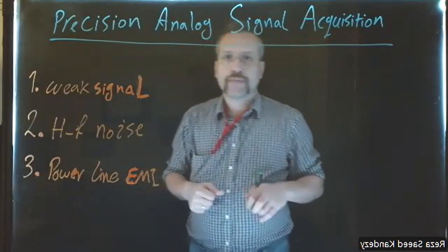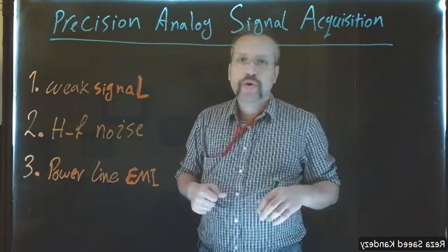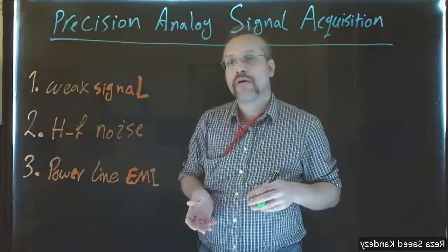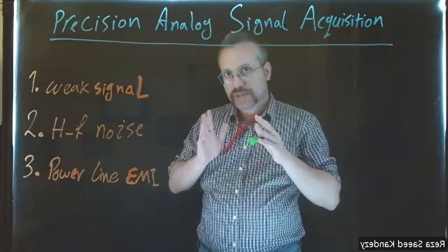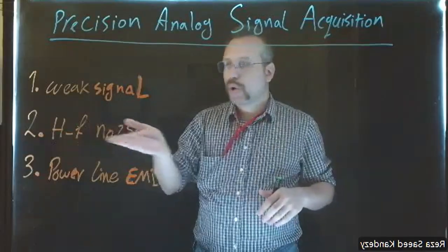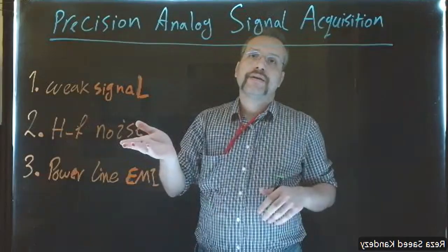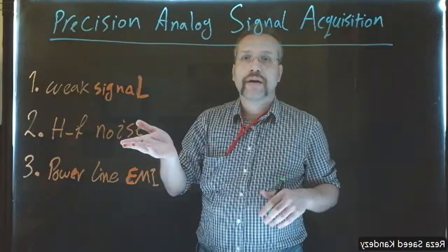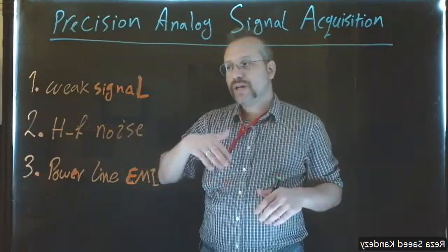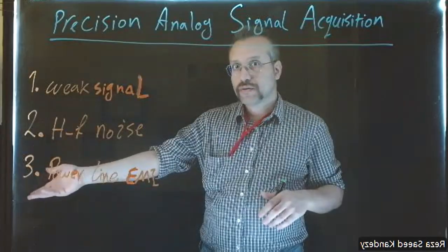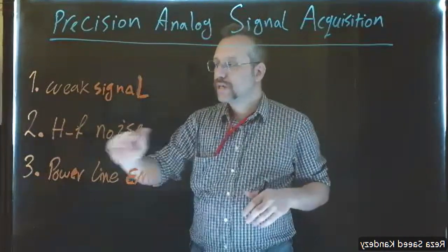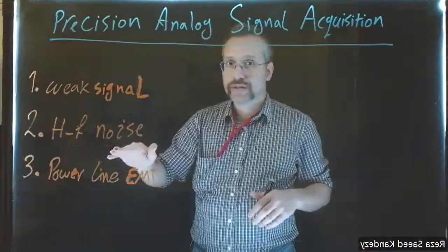Normally, the signals from the sensors are noisy because there's a lot of electromagnetic interference in our environment, most specifically high frequency noise. So this is another shortcoming or pitfall of the signals that come from those sensors. We need to deal with that noise, meaning we need to filter it out. So another problem that we have to address in those signals is high frequency noise.